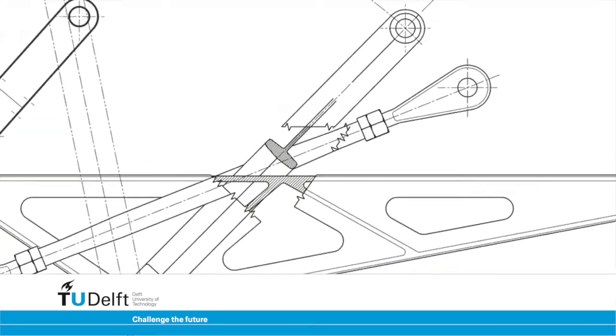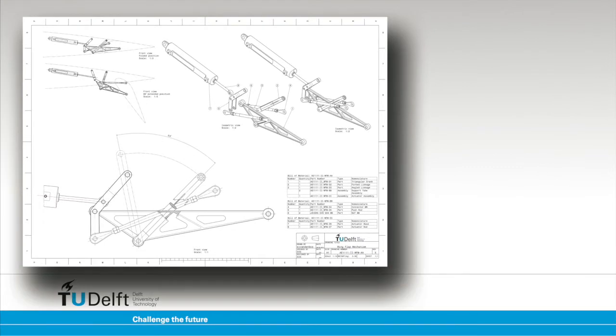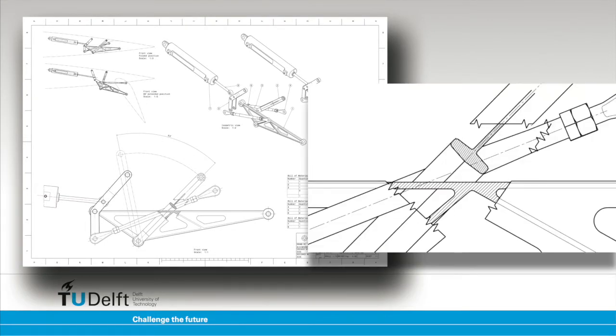Partial section views can be used to show the internal geometry of an object within a projection view. Partial sections do not have section planes. The view is shown with hatching at the section geometry and is delineated using a line in zigzag or thin irregular line type.